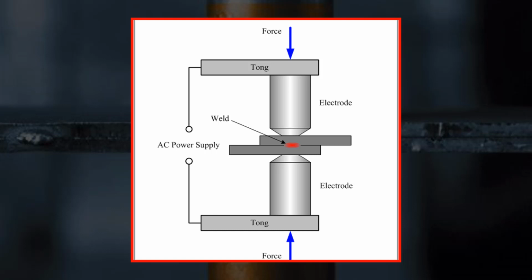With the help of the electrodes, we can generate some pressure, and also a strong, high intensity current can be passed through them. Due to the resistance, this current will be converted into heat. It means electrical energy will be converted into heat energy according to the equation I squared R T. When you pass the current for some time, this electricity is converted into heat energy. Here we are using a power supply, which may be AC as well as DC. Copper electrodes are generally used, right?